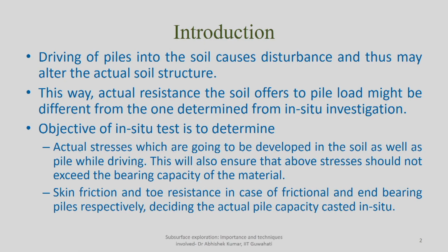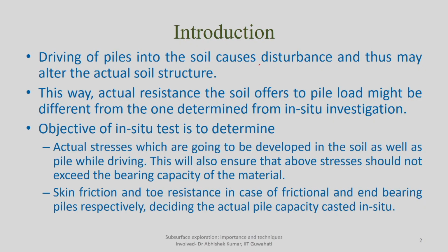As I mentioned, driving of piles into the soil causes disturbance and thus alters the actual soil structure. Once there is a change in the soil structure, there might be a possibility that the actual resistance offered by the soil will be significantly different from the resistance indicated during in situ investigation. Like, you go to the particular site of interest and determine the resistance offered by the soil by means of maybe standard penetration test, cone penetration test as we had discussed earlier, or based on geophysical measurements. But because of the disturbance caused while driving the pile into the soil, which has changed its soil structure, it might be offering a different resistance.